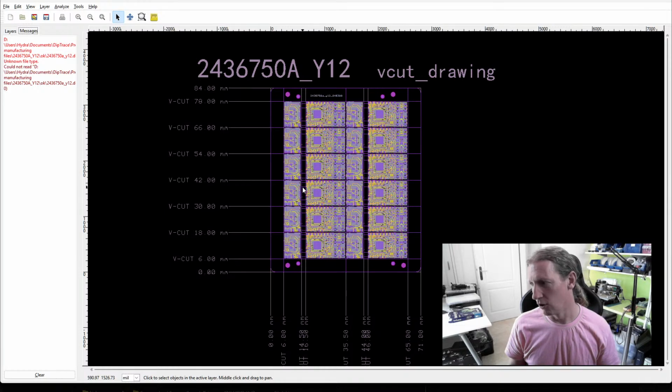Also, there's overhead in making single PCBs versus making a panel of PCBs, such as applying the paste, setting up the job, and making sure all the parts are there. Doing it one at a time is more time consuming than making, say, 10 at a time. That's because of the overhead. So panelization allows you to reduce your overhead. So you want panels. But unfortunately, I don't have any panel definition. It's not in my EDA tool. All I've got is Gerber files.